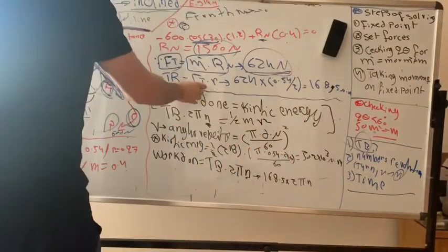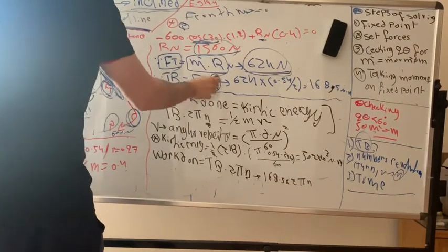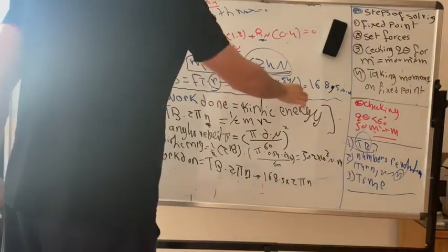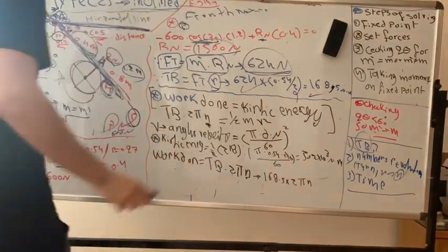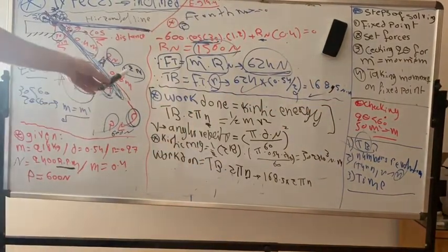Great. So he required from me the TB, the torque. The torque equal FT times R, radius. He gave me the diameter. I divide by 2, and I have the FT, and I got the torque. So here we come, guys.